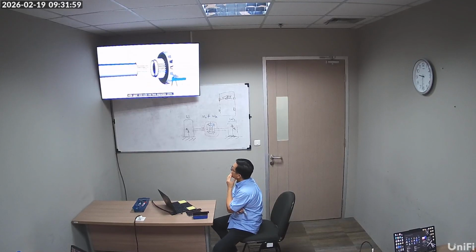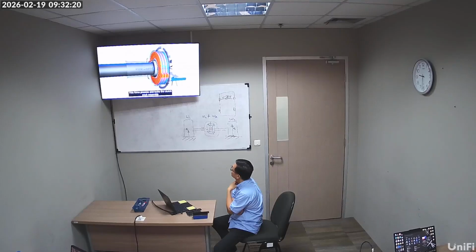You can note that side gear and axle are two separate units. The side gear has got a small allowance for axial movement. So during high torque transmission through the spider side gear arrangement, a high separating thrust force is also transmitted to the clutch pack. This force presses and locks the clutch pack assembly against the wall of the casing.